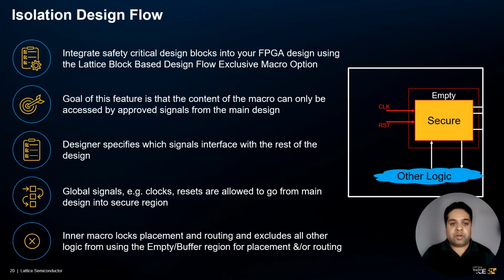Isolation design flow also provides signal specification to the user. Designers can specify which signal interferes with the rest of the design that comes out of this isolation design. Clocks and resets are allowed to go from the main design into the secure region, maintaining necessary functionality.